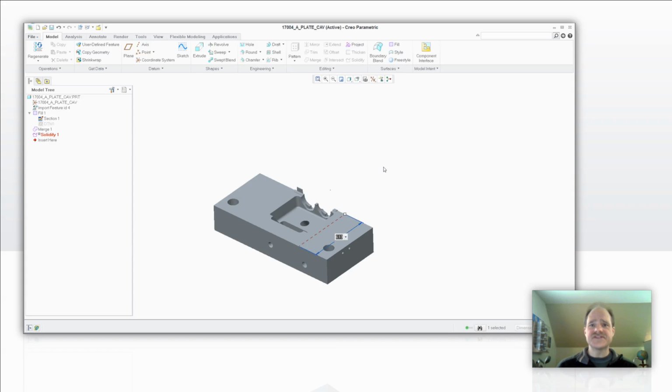If for whatever reason you still can't find it, it's such a small little sliver, once you have this and you went up to the point where you've just got the failure that's occurring, do an intersect between the flat surface you've created and the primary surface of your imported model body. Take that intersecting curve and just start following along that curve until you find that offending geometry. Real easy and simple thing to do.